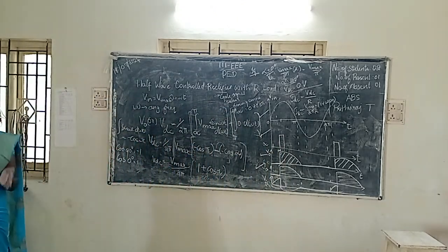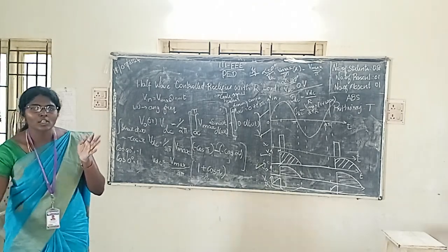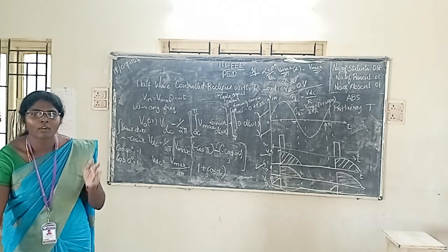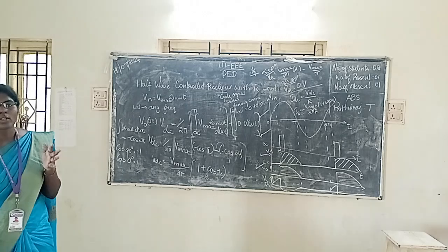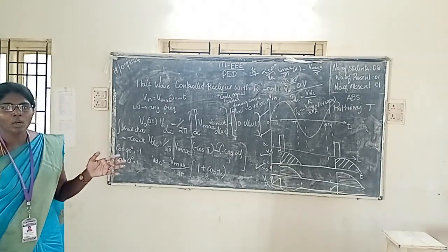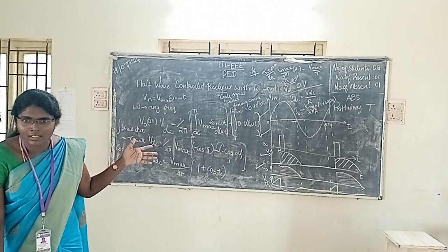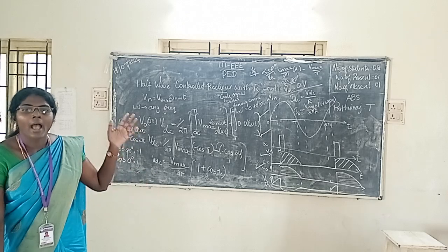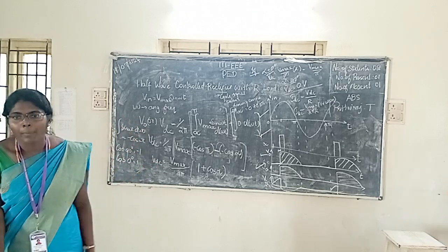Initially, you have the transformer. From the transformer, AC voltage is given. The voltage rating should not be higher than the forward and reverse blocking rating of the thyristor. So this is the rectifier circuit. AC is going to be converted into DC. While converting, how is it controlled? It is controlled by the thyristor's third terminal, that is the gate signal. So we are going to generate the firing angle. The firing angle is represented by the letter alpha, which we generate from 0 degree to pi.